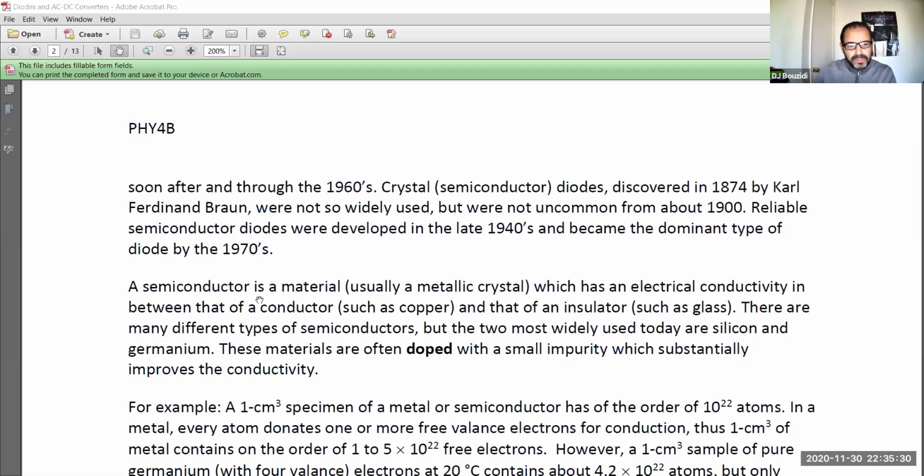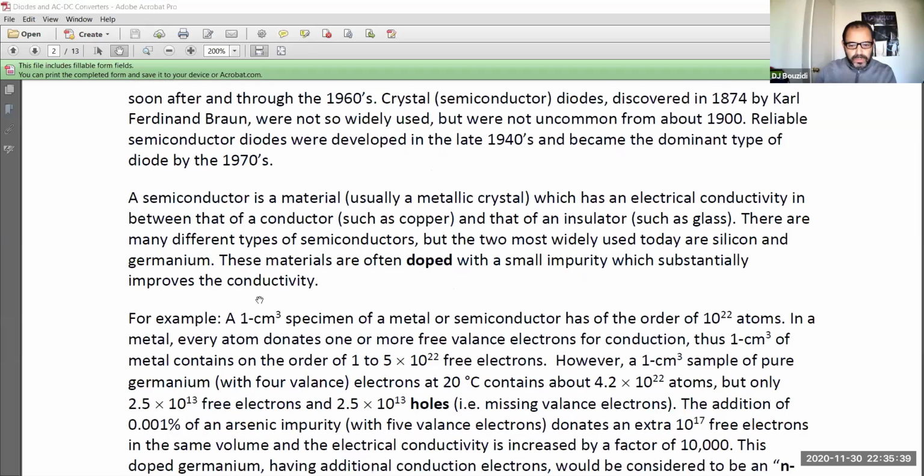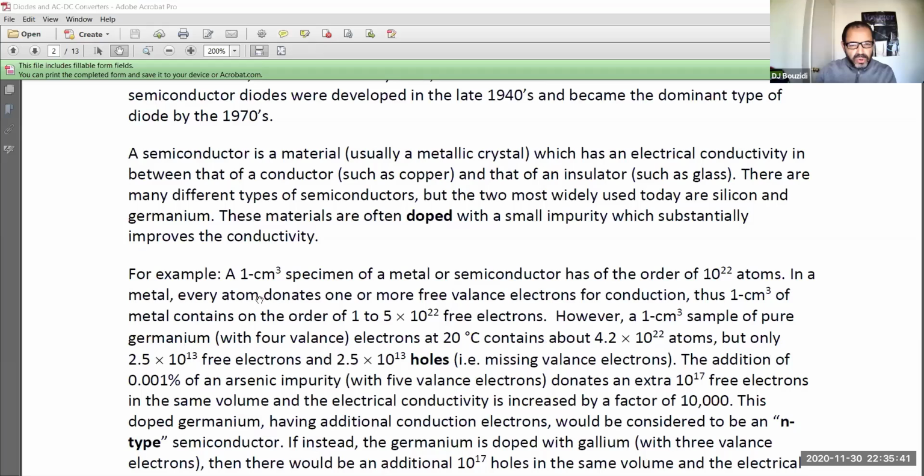When you do add impurities, there are 2 kinds of impurities. Those that have, if you wish, extra electrons in them, and this is the N-type doping. And those that have less electrons, with an affinity for electrons in the opposite direction. In this case, you will have holes, as they are called, that are missing electrons. That's exactly what they are. So both of them will have conduction.